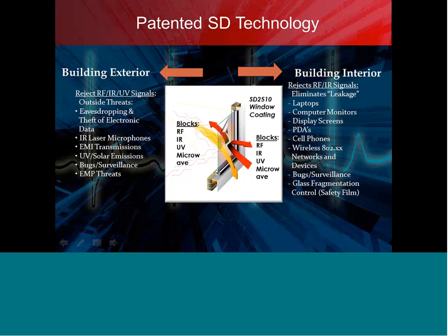So that's a pictorial of how it operates, but that's a key component because the windows as is, whether they're low E coated or not, you get relatively no attenuation, maybe 5 dB of attenuation. The walls, even without the foil, are going to give you maybe 10, 15 dB. So we're looking to lower that level as far as we can.